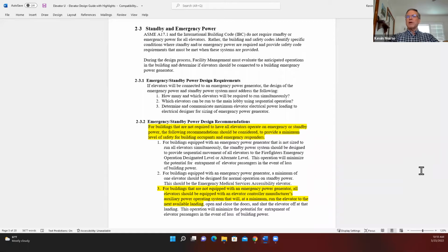The hydraulic elevators will run down, but just by opening the control valve. Traction elevators will run to the next available landing depending on the path of least resistance. The load in the car will determine that.